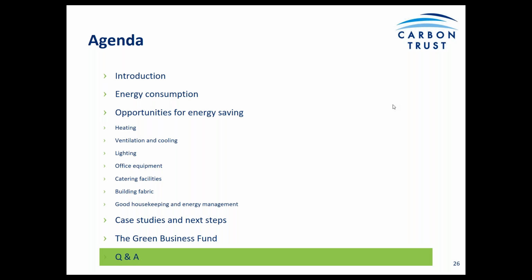Options for energy saving boilers, assuming that it is a gas boiler. So modern condensing gas boilers have seasonal efficiencies of up to 91 to 91.5%. So that's normally what we suggest if you are looking for a like-for-like replacement of a commercial or domestic boiler.